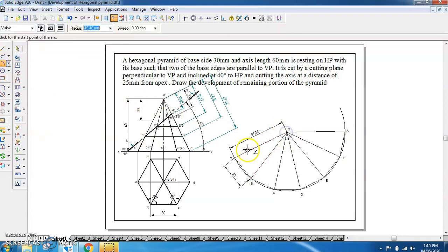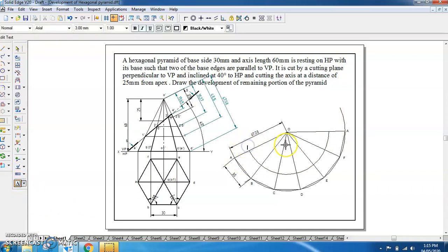Now we start with the point 1, arc by center point. So you get this arc on this edge, that is distance 48.15. Enter it. From this point to this area, you'll be getting 2 points. So mark this 1 point here, and this is also 1 point here. Now the second point we have at a distance of 35.37. So enter 35.37 from BO till FO. So you will be getting this as point 2 and this as point 6.